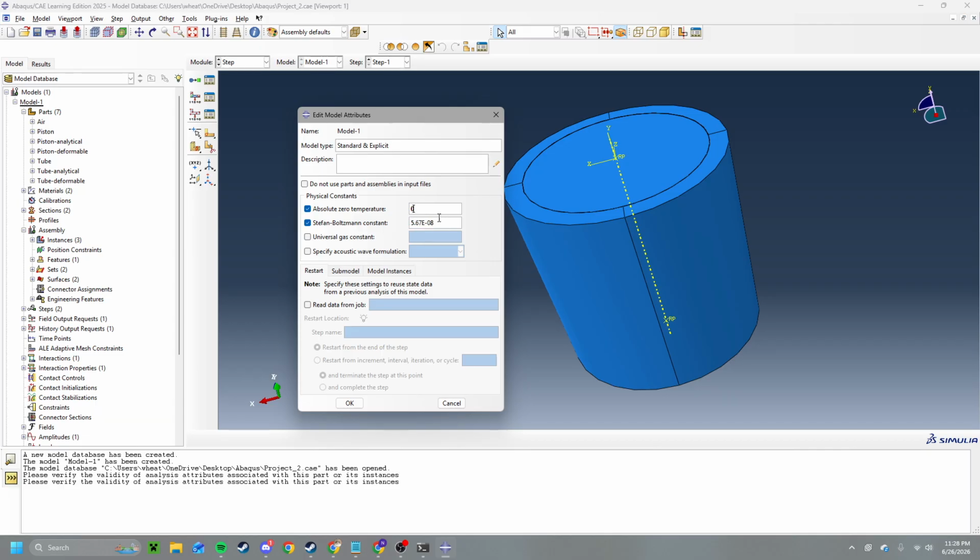You're allowed to set these to whatever you want because Abaqus doesn't enforce types or units, so you have to set these to whatever units you're using. I was using meters, newtons, pascals for all of mine, so I use these values, and Kelvin.